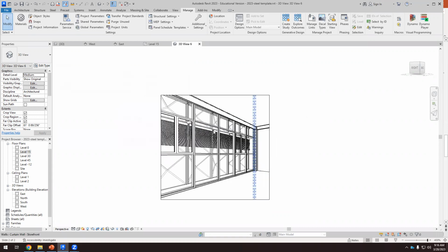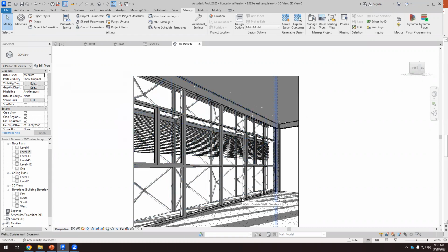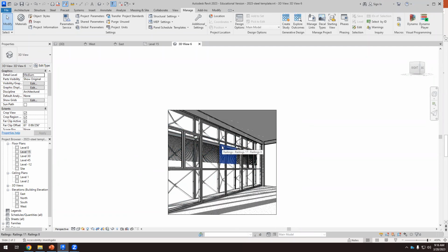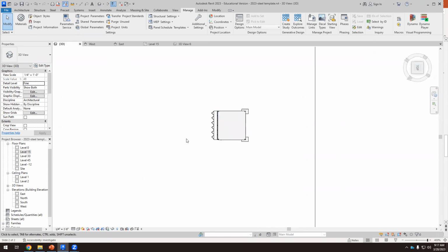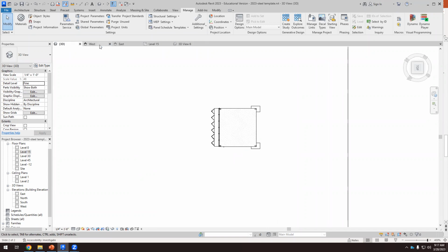Okay. But these kinds of double skin facades make sense on south elevations, and on east and west elevations. They don't make any sense on the north elevation, because on the north elevation we don't get any sun. We can make the most of the sun, and there's no point in having all these shading devices on the north elevation. So I wouldn't do that in the north, but on south, east, and west, this kind of double skin facade can work really well.